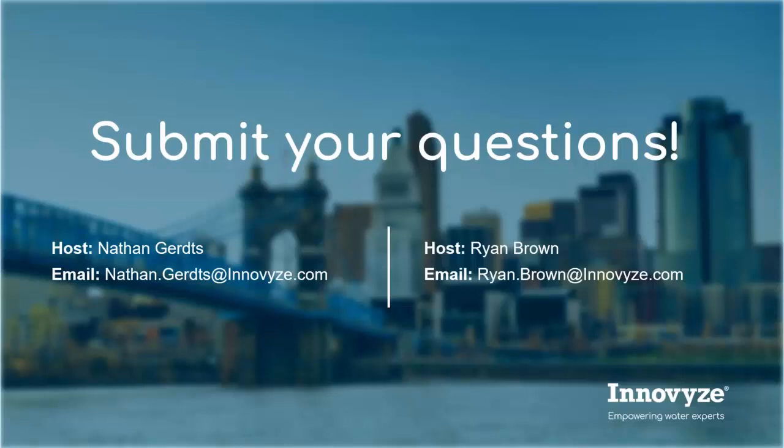Okay, there's a couple questions about the EPA SWMM models and integrating it. I think you touched on it, but specific to SWMM 5, are there any issues with integrating that into InfoWorks? Yeah, I'll take this one. We set it up so that you can use a SWMM 5 engine within ICM, and if that's what you want to use, you can import it, and you will get the same results.